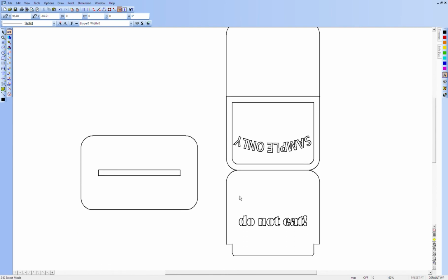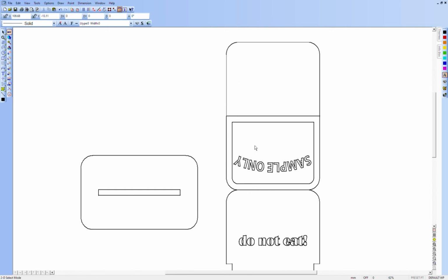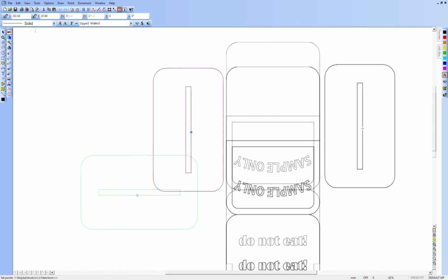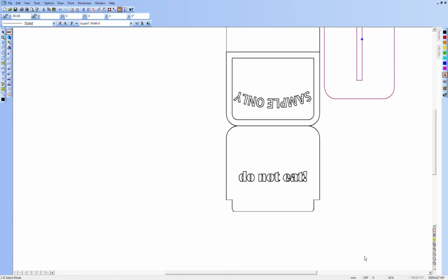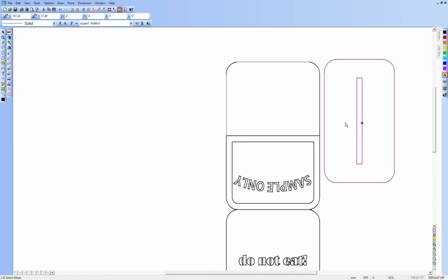We're going to need 2 copies, so we'll copy and paste the base when the time comes. In terms of layout, if we put these parts above or below the stack, we're going to create a thin vertical strip of unused wood beside the stack and between the overhanging bases. Not great. But if we take this first copy and rotate it 90 degrees, we can see that we could put both copies of the base right along the right side of the stack. This would use the top right corner of the wood without leaving any little pockets of useless uncut wood trapped in the middle of our cut.